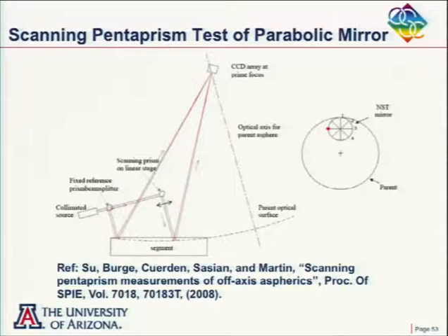So how long has the pentaprism test been around? I first knew about it in the 1960s, so I don't know when it was. I would like to comment on that. Actually, the beauty of the pentaprism is that it's insensitive to rotation, so the wobbling is not from that rotation. It's kind of the height. As you change the pentaprism, the angle of the beam coming out doesn't change. That's the beauty of it. I thought it might be moving to a different location or something, is the problem. Not a location. Yeah. But that's the nice thing about the pentaprism, that the angle stays the same.